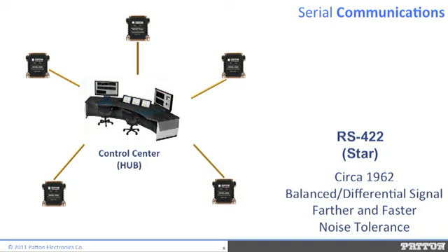Unlike RS-232, the RS-422 standard only defines the electrical parameters for a balanced circuit, so it uses twisted pair. The twisted pair offers immunity to electrical noise. It's a good fit in the industrial world's applications with a single master and multiple receivers. It can be used in point-to-point, multi-drop, or star technologies. If used in a multi-drop topology, it is commonly used for sending programs to PLCs.